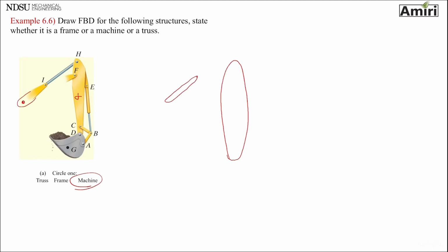and I think it's a two-force member, so whatever I put on there, I am going to do it this way. Point H is common, so it needs to have opposite and equal direction. Point F, let's assume that there's another two-force member. That's fine. The other way is whenever you see a pin on a member, just put an X and Y for it. So let me just put an FX and FY for it.